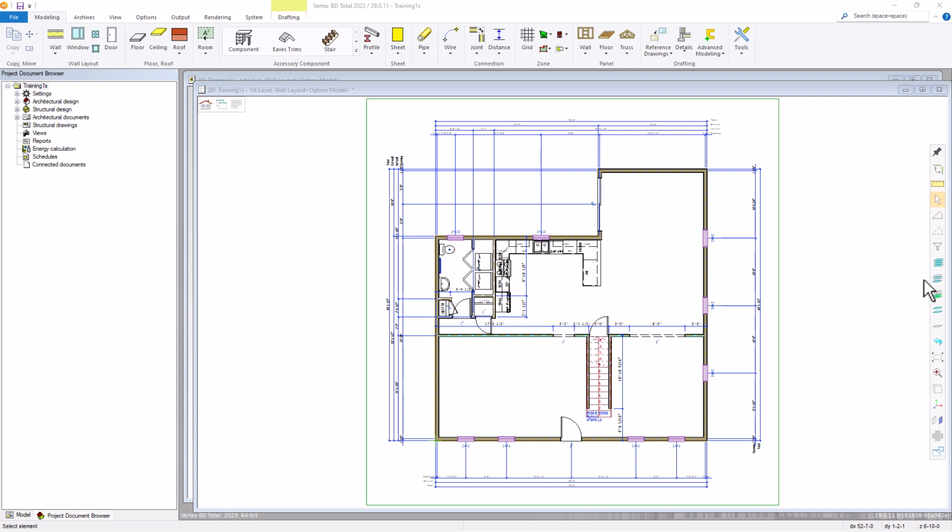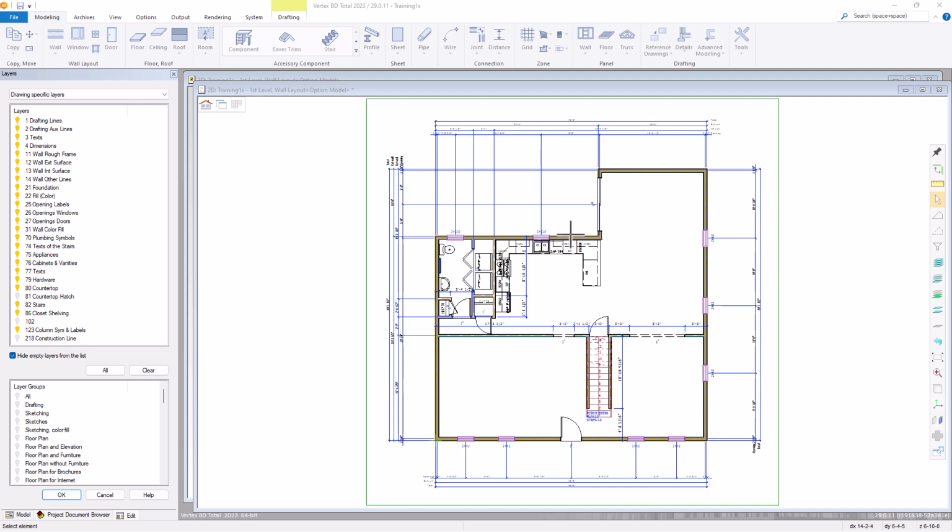You can find the layer groups from Select Layers from the list. Over on the left-hand side, you'll see a panel open up. Down at the lower section, there's a layer groups. Scroll down until you find one called Rooms. This will have the predefined layers turned on and off for the Rooms layers group.